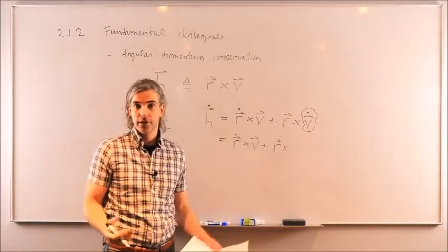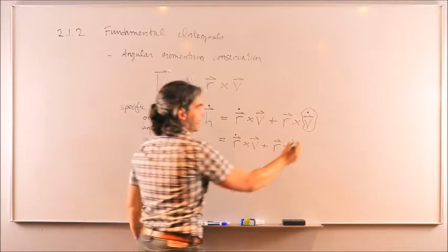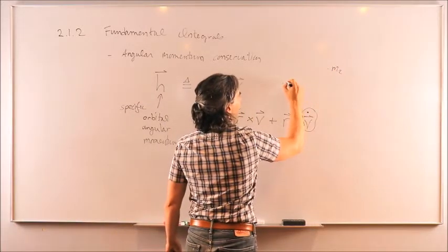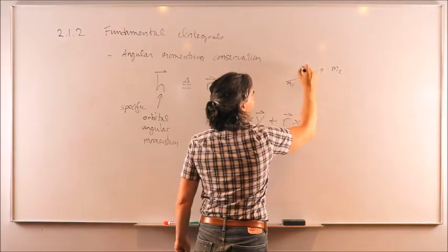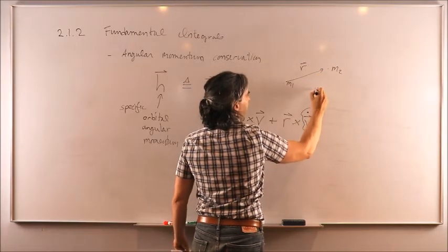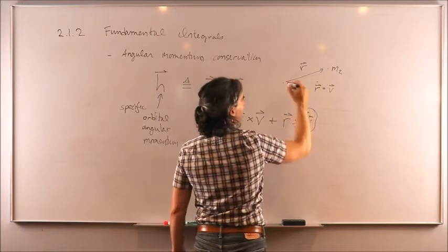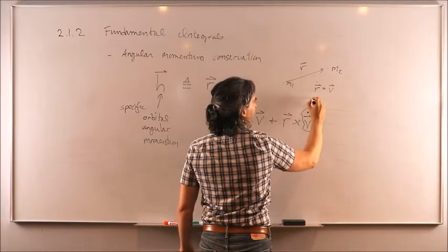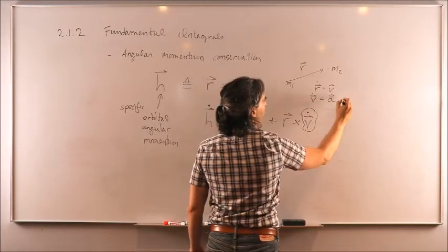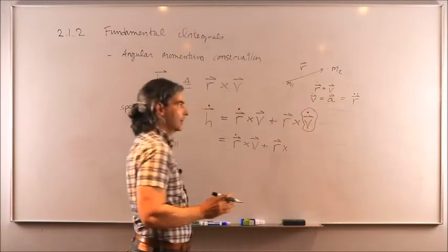Well, obviously this is my inertial acceleration. Acceleration of what? Acceleration of m2 with respect to m1. Right? If this is r, then the derivative of r is my velocity vector of 2 with respect to 1, and such that v dot is my acceleration, or I'm going to say double inertial derivative of my position vector. It's all the same.